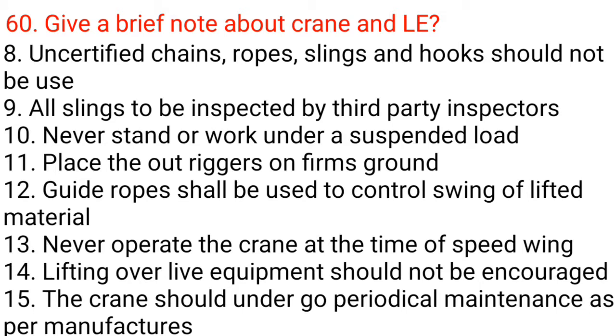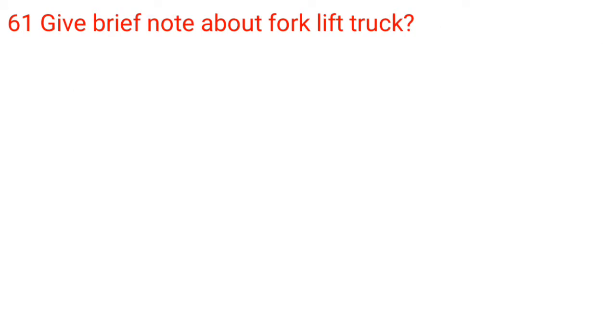Never stand or work under a suspended load. 11. Place the outriggers on firm ground. 12. Guide ropes shall be used to control swing of lifted material. 13. Never operate the crane at the time of high wind speed. 14. Lifting over live equipment should not be encouraged. 15. The crane should undergo periodical maintenance as per the manufacturer's guidelines.